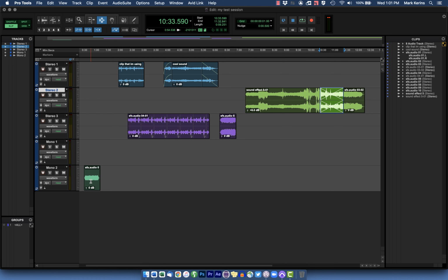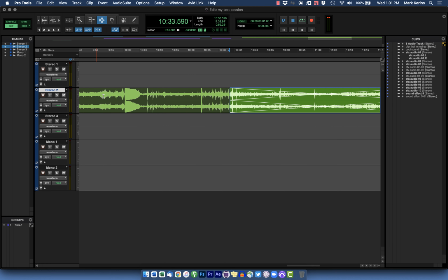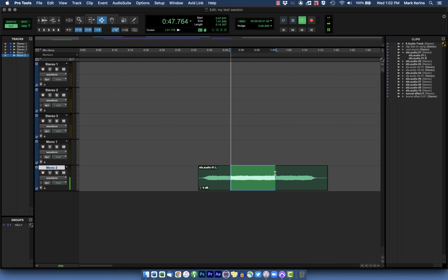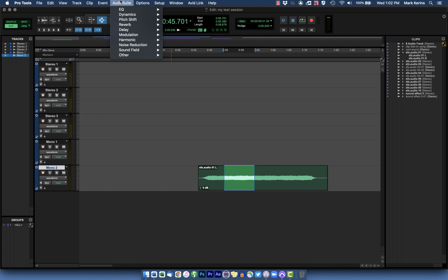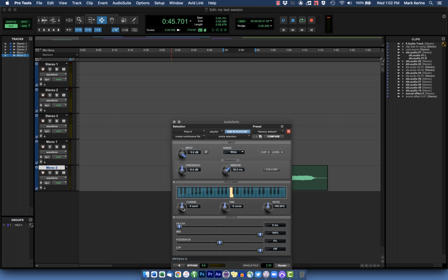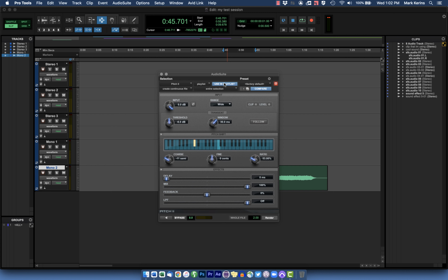Last thing I want to show you here is Audio Suite, and I'm not going to get into all the details on this, just show you it exists as you're getting started in Pro Tools. And so let's say a little piece of audio here, just kind of this tone, and I want to do some sort of processing to it. There are different ways to do this within Pro Tools, but the simplest way when you're getting started out is to just use Audio Suite here, and you can see all these different processing things I could do to it. So for instance, let's say I just want to pitch shift it. Use the Pitch 2 plugin, and I'll just shift it down a bunch there. Make sure Use in Playlist is turned on if I want it to actually show up in my session here.